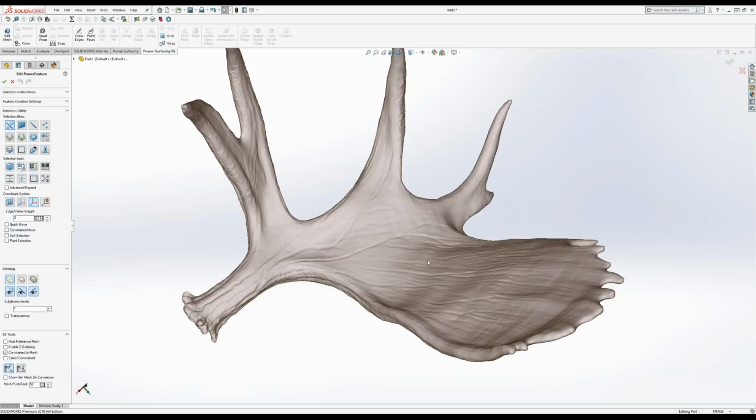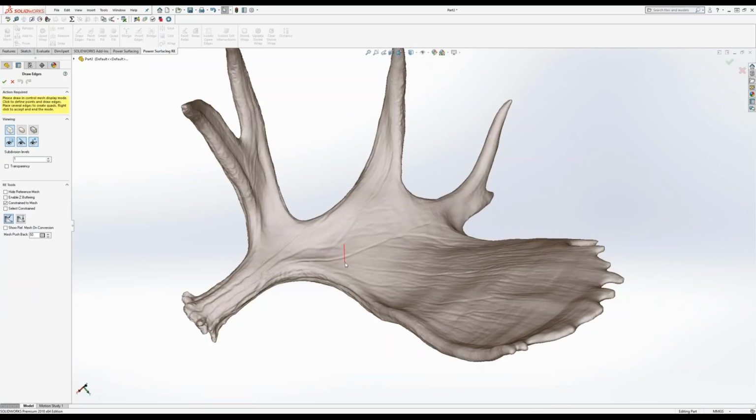it's kind of a very squarish thing. Let's say you typically have something fairly flat with a bunch of holes in it. What we do is fill those holes in, and then they tend to be very flat. So we may, for example, just put a square on top of it, and then subdivide that square to get the same thing that we're doing here, instead of using the quad wrap. Typically you're a little better off if you lay out the mesh by hand, which you can do fairly easily. So let me show you how you can work the mesh by hand.